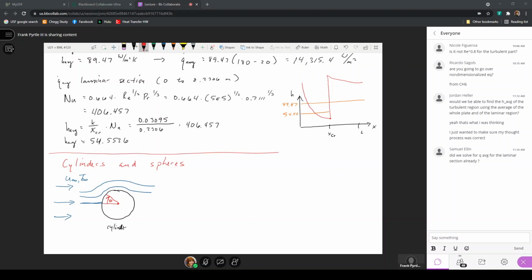I think it typically goes from 0 to about 160 degrees, there's a variation of the Nusselt number as a function of theta. And if the Nusselt number is defined in terms of the heat transfer coefficient, that means the heat transfer coefficient varies as we move around this cylinder. That just says that the local heat fluxes around the cylinder are going to be different.